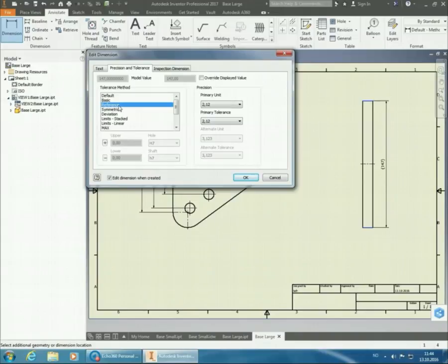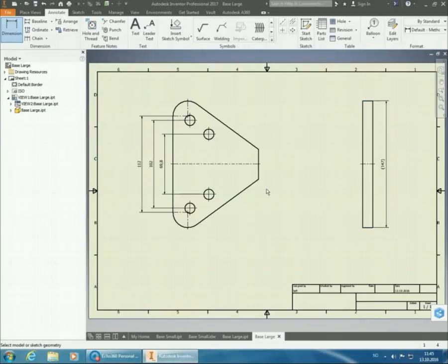Because the only reason we're putting in this dimension is to make it very easy for the machinist to control it, that the dimension is approximately 147, and then if it's way off, he'll have to go in and start looking at where are the center points on these rounded edges and what are the exact radiuses of the edges, because then you have to use special measuring tools in order to get those dimensions. It's much easier to just do a linear dimension across the entire length there to check that you're within your tolerances. So we put this one in place.